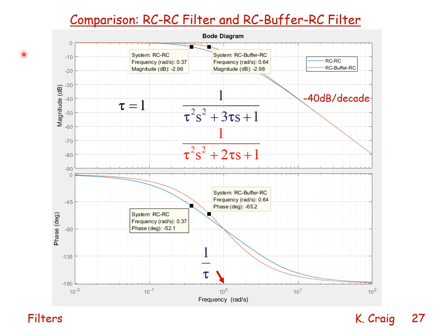One last comparison to complete the study. Here we compare an RC second order low pass filter where the downstream RC filter loads the upstream RC filter. And I compare that to the second order filter with a buffer op amp, a unity gain buffer op amp that prevents the downstream filter from loading the upstream filter.